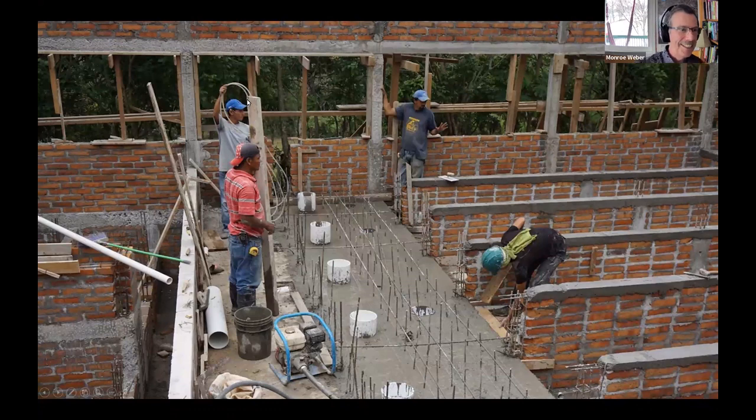And I'm curious, has anybody seen construction in other parts of the world where you don't actually use a theodolite to do leveling, but instead you use a water hose? So it turns out this is a pretty accurate way of doing it. That water hose is transparent, so you can see the water inside the hose, and you set the hose up so that there's a little bit of air at the end of each end of the hose, and you can use the water level in that hose.